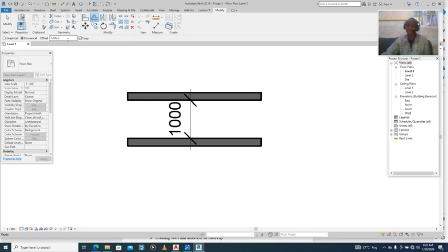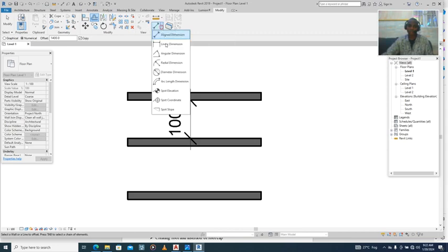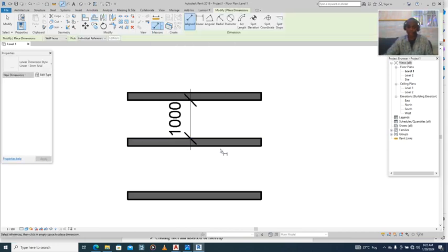Assuming I want to offset 1200, I'll do what? Add the thickness of the wall. So it should be 1400 now. I'll come here and offset. I'm offsetting down 1400. Let me dimension it now. Align dimension, click on this face and click on this face. You see, I'm having an accurate 1200 distance offset. So what point do we get here? Whatever we wish to offset, make sure we are adding the thickness of the wall we are using for the modeling while offsetting. All right, good.